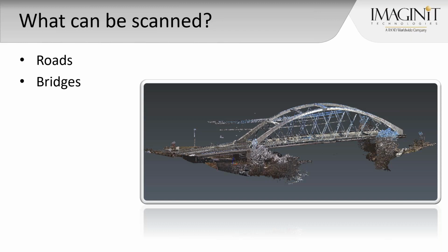doing traditional survey methods? Well, by scanning, keep in mind that we are shooting that laser over a distance. Depending on the equipment, that distance might be 100 meters. It might be 200 meters. Okay? In some cases, it might be a kilometer. How does that benefit us? Well, that benefits us because we're able to collect large amounts of data, and we're able to collect it without ever putting somebody in the roadway.